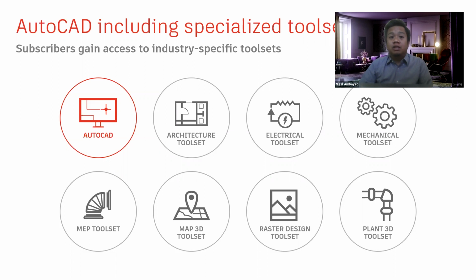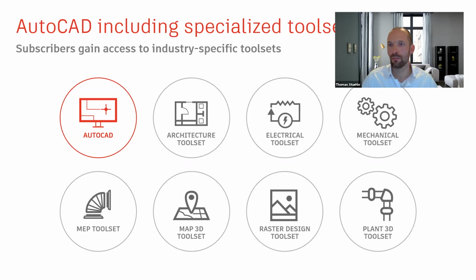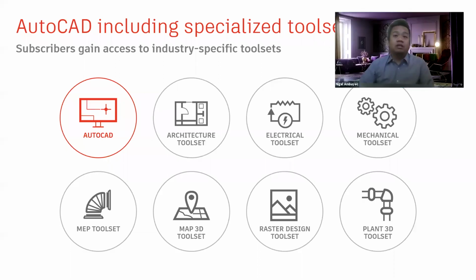Backwards compatibility and file version. Are the file versions the same as last year's AutoCAD? Yeah, 2018. Cool. So like in all AutoCADs, they are pretty much backwards compatible when it comes to vanilla, and you can back save into older versions. That brings me to this point too: when you're utilizing some of these verticals, sometimes you don't have the same backwards compatibility depending on which one you're using. So if you have any questions about that, let us know here and we can go ahead and answer those questions for you.